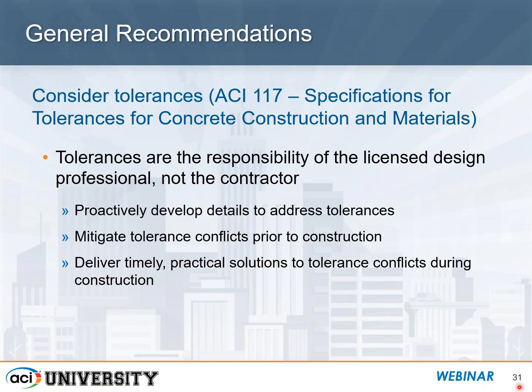And again, that's looking at these special intersections where beams and columns are all coming in and taking into consideration what the tolerances are for the placement of the reinforcing bars and the size of your structural members, giving a little breathing room, adding maybe a little cover here and there just for an example.